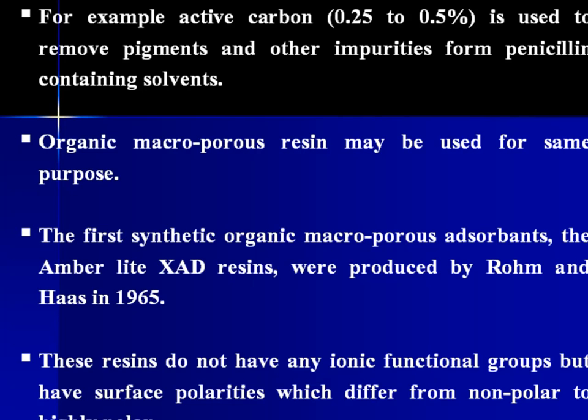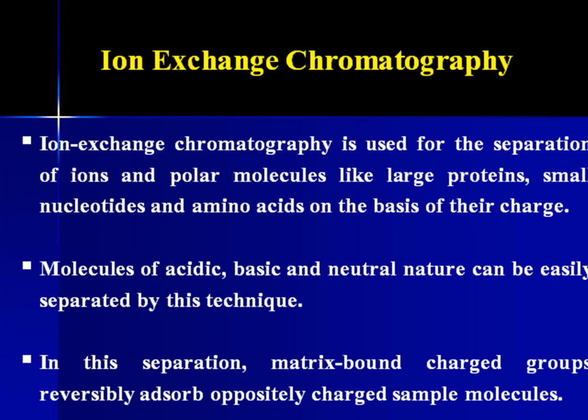The first synthetic organic microporous adsorbent, the Amberlite XAD resins, were produced by Rohm and Haas in 1965. These resins do not have any ionic functional groups but have surface polarities which differ from non-polar to highly polar.